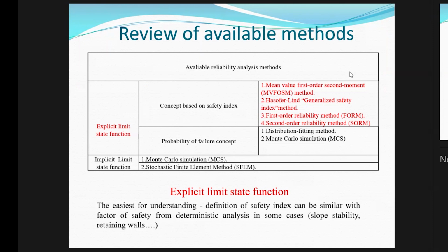When we perform some engineering analysis, we have some input variables like strength of the material, loads, and so on. Especially in structural engineering, for example for concrete, we have a certain design strength, but we always know that when you take a lot of samples and do the statistics during the construction works, certain specimens are below the design level, some above, and some kind of mean value should fall into the design value. So this is one kind of material uncertainty.